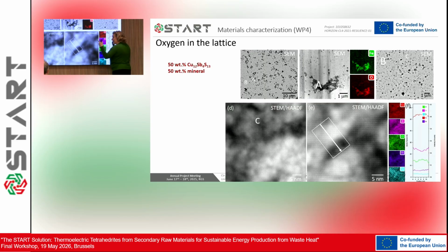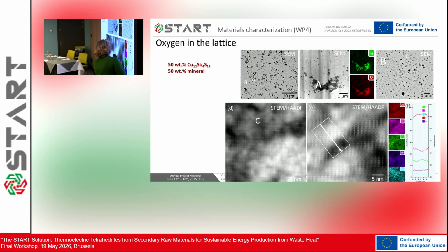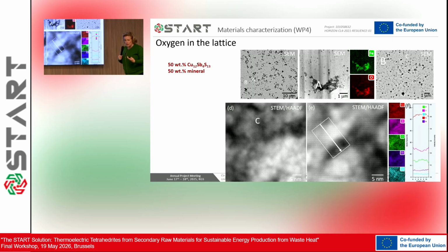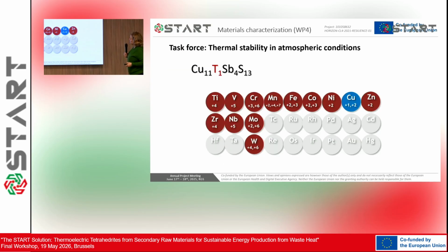And now this is in the structure of tetrahedrite, because this is just the same crystal. You're seeing it in projection, this is TM. It's the same crystal, and what you're seeing is that there is a difference here. You have not so much iron and oxygen, and here you have more iron and oxygen, and also copper. So it's much more complex, and we need some sort of a metallurgical way of looking at this problem, because otherwise, if we don't go deep into the microstructures, we don't understand what's going on in terms of thermoelectric properties. Now I'm going to present the last case study.